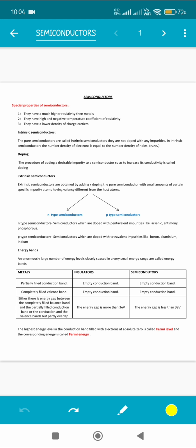The semiconductors which are known as intrinsic semiconductors are devoid of any sort of impurity. They are just tetravalent atoms, for example silicon or germanium, without any impurity. So they are not enhanced in any manner for increasing their conductivity. Also, in intrinsic semiconductors, the number of free electrons will be equal to the number of holes. A hole is nothing but a vacancy or an empty space in the energy band. We'll come to that later. Since we are not adding anything extra, the number of holes, NH, will be equal to the number of electrons, Ne.